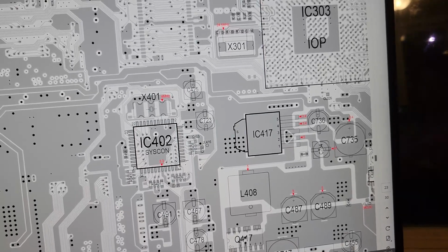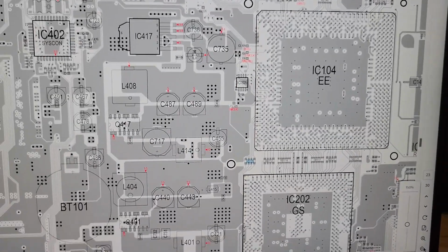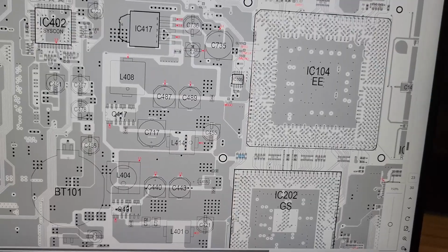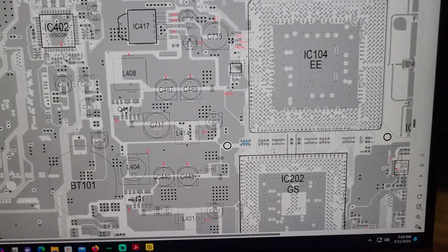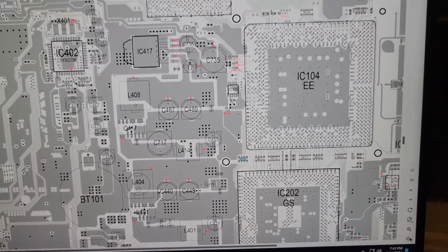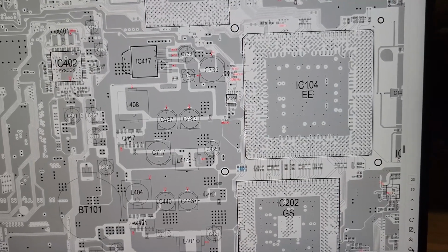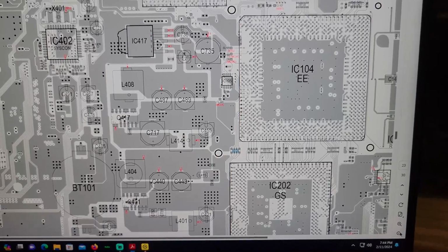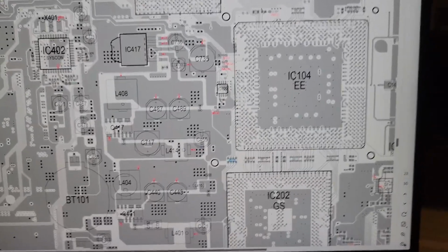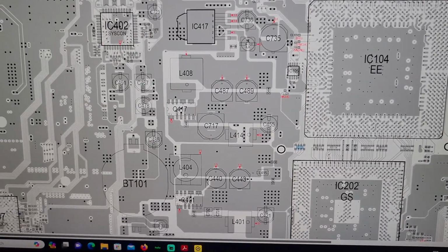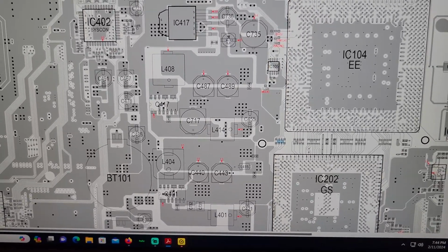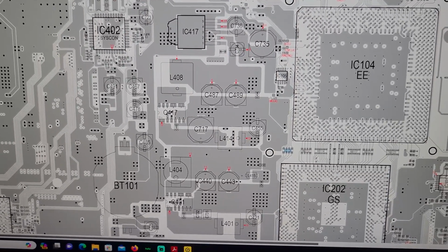But yeah. Like I said, that's usually your GH-19 no video issue. Or if you have a distorted image or something like that, it's always those network resistors on top on side A. I want to buy one to show you that for proof, because I had that board in there for months and months and months.